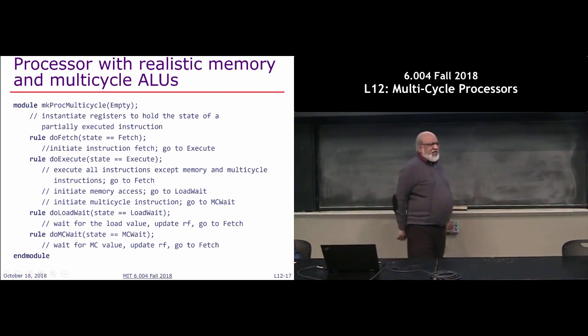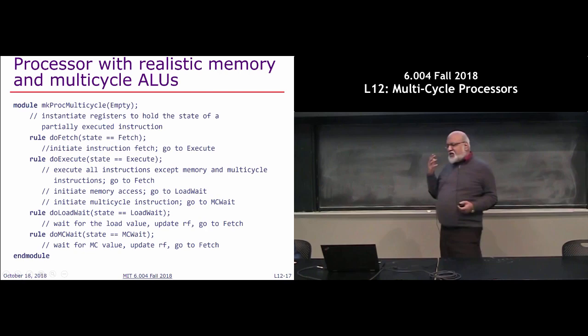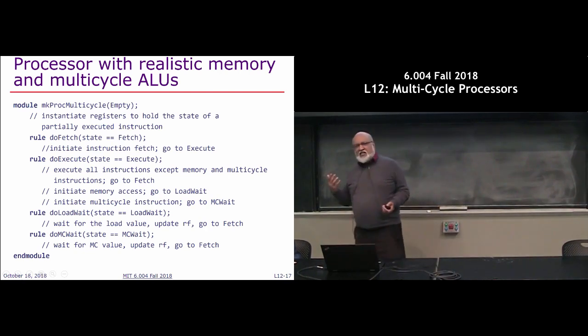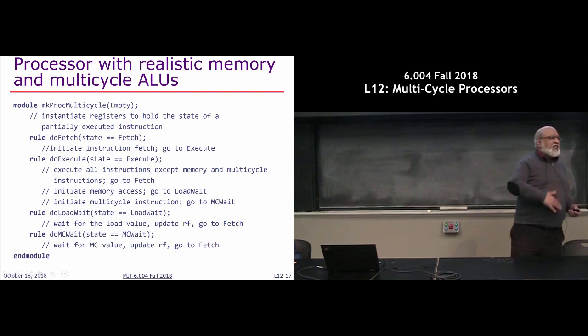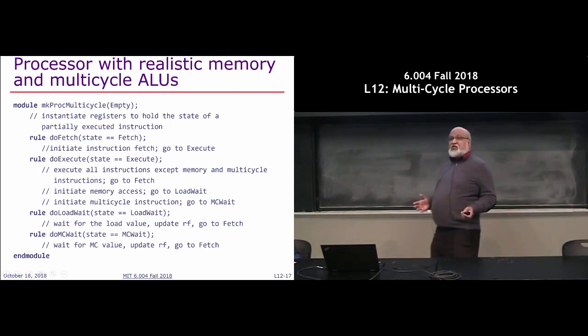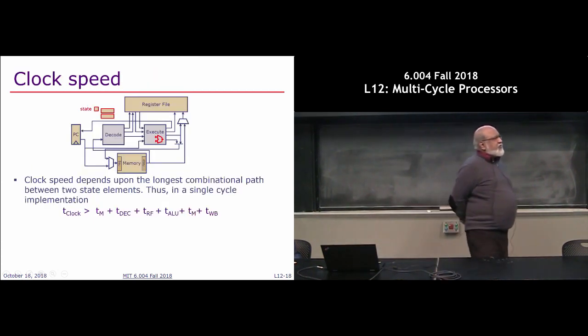What my goal here is to teach you the generality of it, right? You should be able to deal with multi-cycle things. If something is taking too long, break it down, right? Make it request response so that it remains latency insensitive in some sense, or oblivious to how long operations take. And the framework we are providing here in terms of atomic rules and doing it like this is extremely general. You can express many different architectures very simply in this manner.